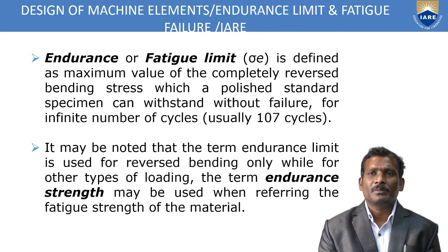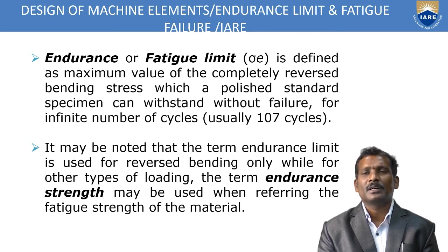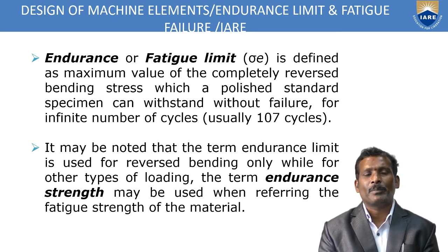The endurance or fatigue limit is the maximum value of the completely reversed bending stress which a polished standard specimen can withstand without failure. So already we have tested one specimen, and the limit which that specimen can withstand without failure is called the endurance limit. That is the higher limit value, the endurance limit or fatigue limit in the case of fatigue loading. In the case of normal loading, a tensile or compressive load, generally we take the ultimate stress, which is the maximum point.